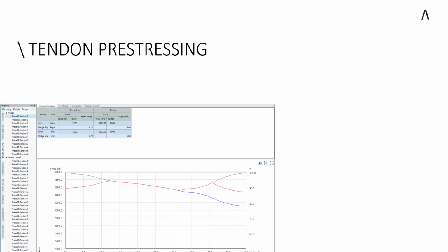Okay, for the tendon properties, the material I noted before is already for the outputs of the pre-stressing. If I have inputted the material, the area of the tendon, the alignment and all these things, I can then, with the tendon model, with the pre-stressing model, let the program get the output out of it.